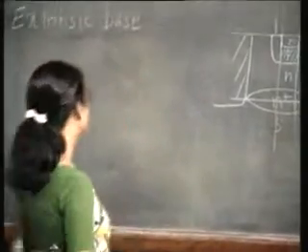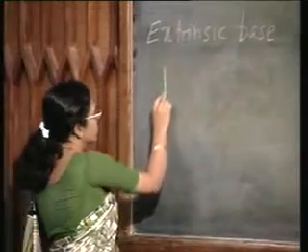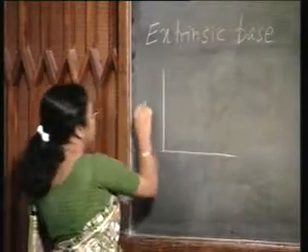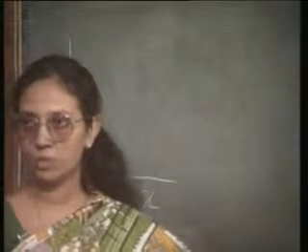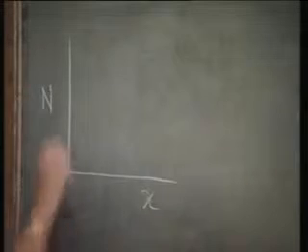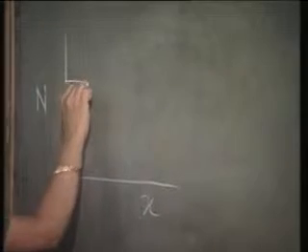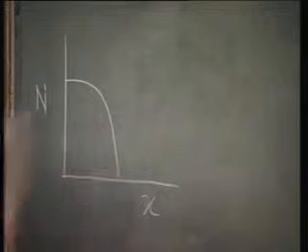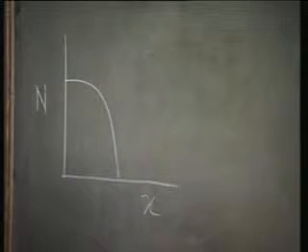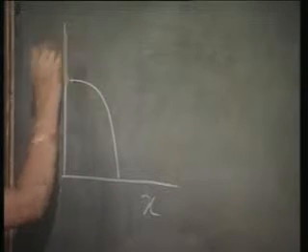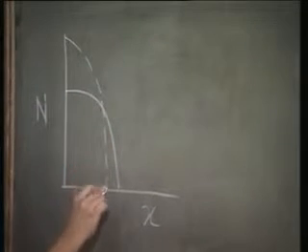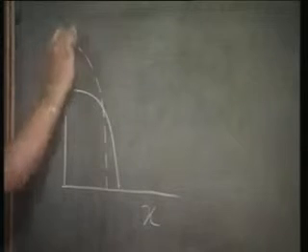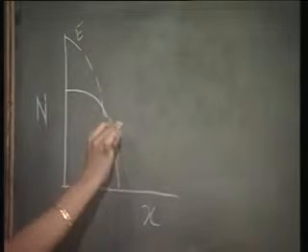How? Let us see. Suppose what I am trying to plot is the doping concentration with the distance. Now, let us say I use an implantation profile like this for the base region. And let us say my emitter doping is going to be the dotted line is for the emitter, the solid line is for the base,